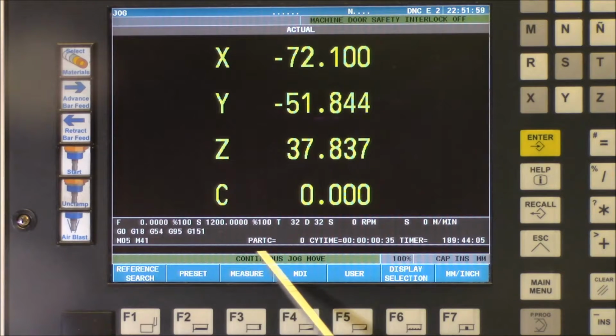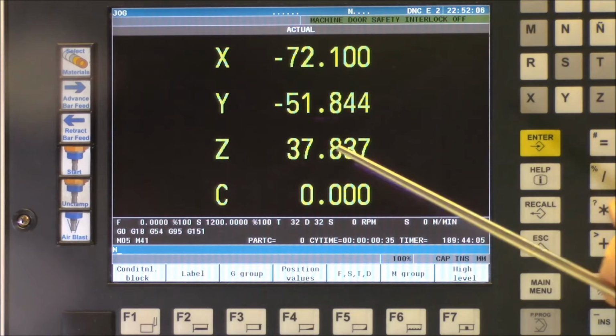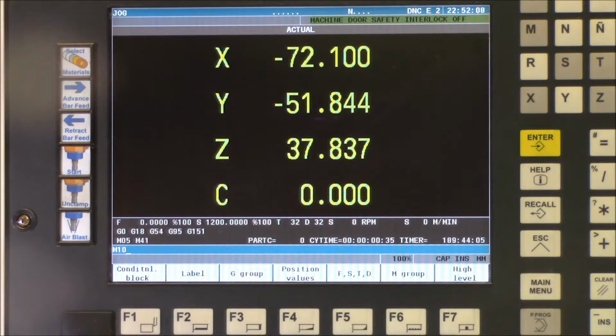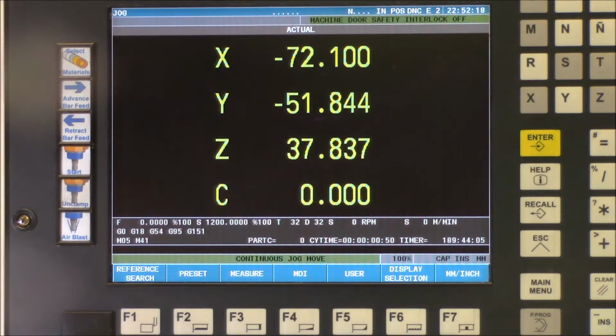This black line is used in MDI mode. If we use MDI, it turns blue and it's for entering data input. In this instance we'll type in the simple M code and press cycle start. You'll see it is accepted and we'll exit out of MDI mode.